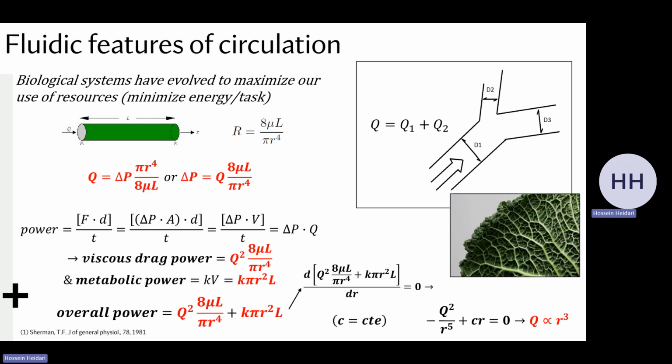Now, if you actually take that and put it up there, you'll see that this is the final equation: the diameter or the radius of the inlet to the power of 3, so the cube of that, has to be equal to the sum of the cubes of the outlet diameters. Now, this is a very key equation because that equation is the exact equation that helps us answer the question of, are we increasing the overall cross-sectional area or are we decreasing it?